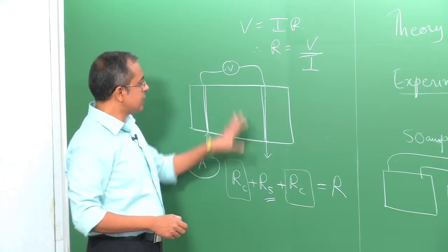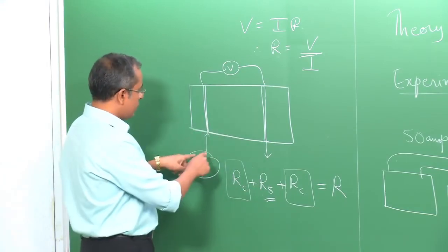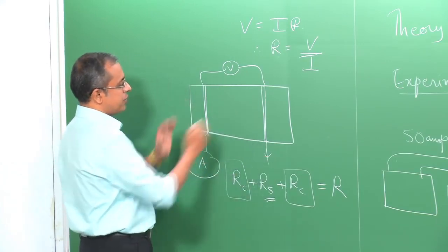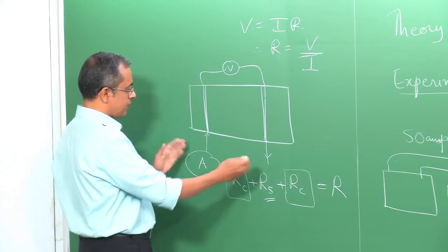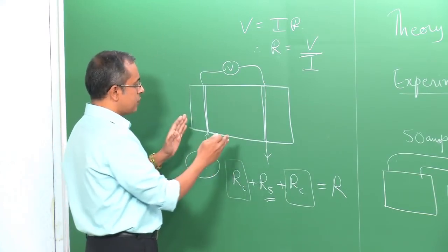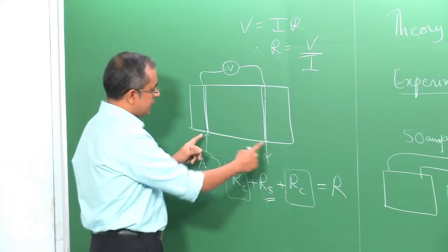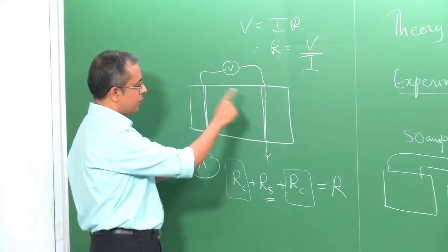So, this is called a two probe measurement, wherein the entire process of connecting to your sample, through the power source you are applying, occurs only at two locations, this one and this one. At the same two locations you are checking the voltage, and the current flows through the same two locations.